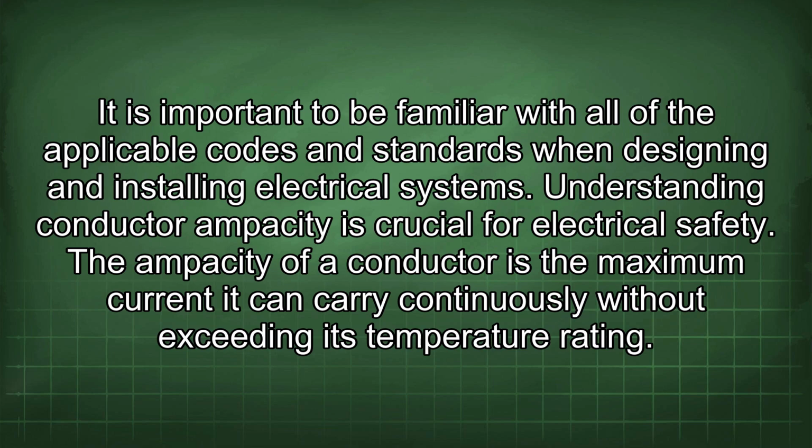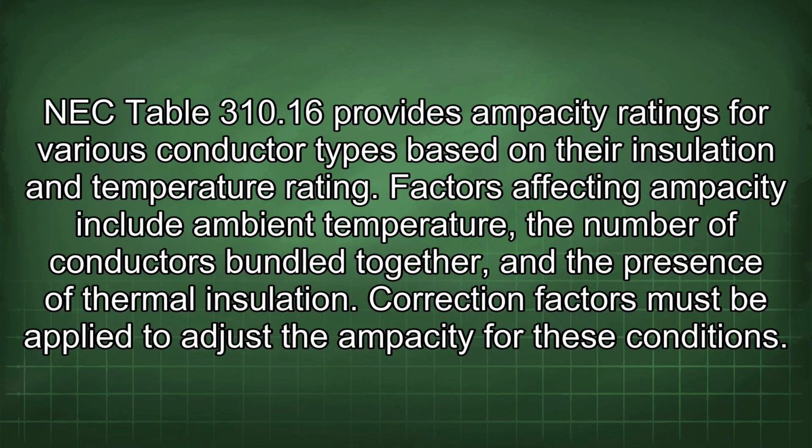Understanding conductor ampacity is crucial for electrical safety. The ampacity of a conductor is the maximum current it can carry continuously without exceeding its temperature rating. NEC Table 310.16 provides ampacity ratings for various conductor types based on their insulation and temperature rating. Factors affecting ampacity include ambient temperature, the number of conductors bundled together, and the presence of thermal insulation. Correction factors must be applied to adjust the ampacity for these conditions.